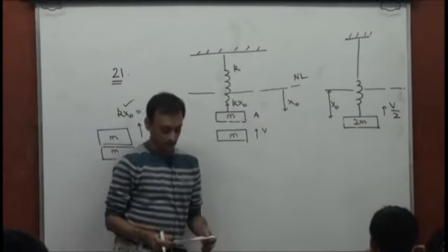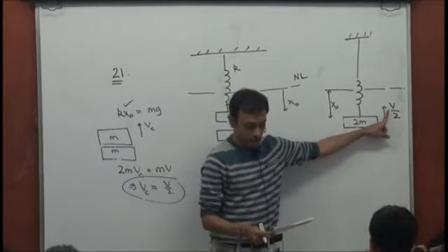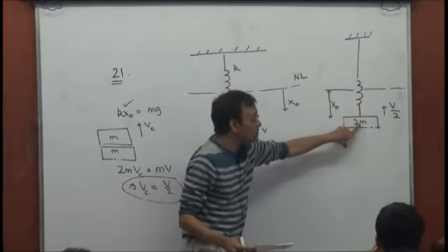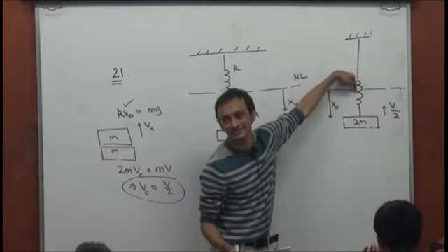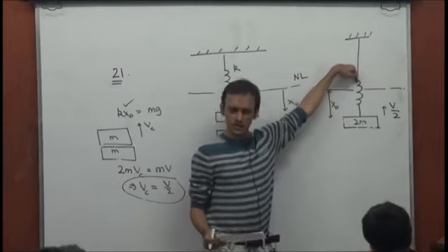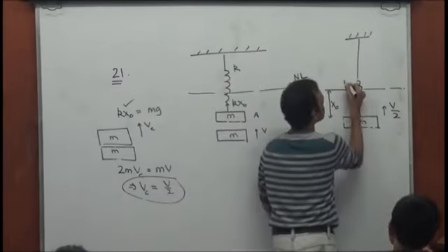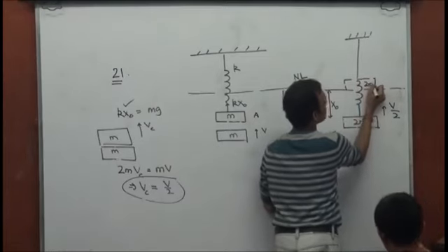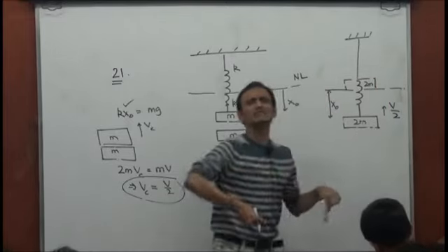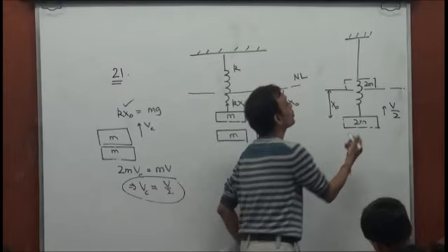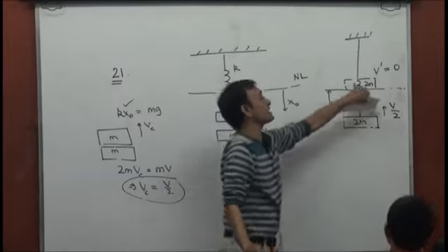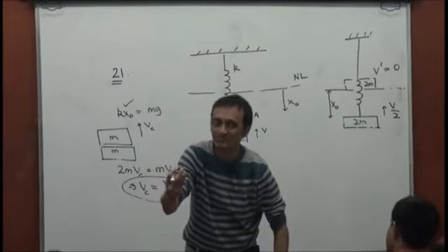Now, what is it that we are seeking? The value of v, so that the spring just about attains its natural length. That means we want this mass 2m to just about manage to arrive at the natural state of the spring, right? That means we want the mass 2m to arrive at this natural state with just about arriving meaning arriving with a velocity 0. V prime being 0. So between these two states, can I not apply the work energy theorem, right?